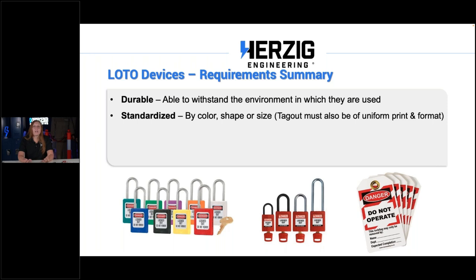It doesn't matter what color you use. It doesn't matter what style you use, as long as they are single keyed locks and they're consistent. For example, I know there's a lot of companies out there where the electrical department gets all red locks, and general maintenance gets all blue locks and so forth. That's fine as long as the other parts of it are consistent. And the other side of it, they don't really care what type of lock it is, but all red locks are LOTO locks and can only be used for LOTO. That's fine too. See what I'm saying?